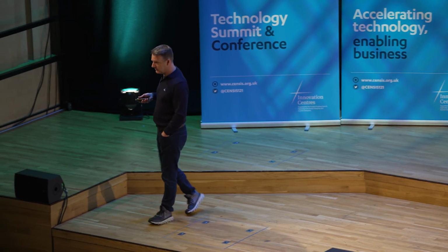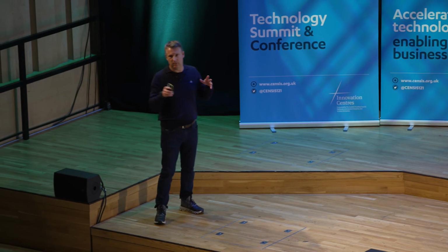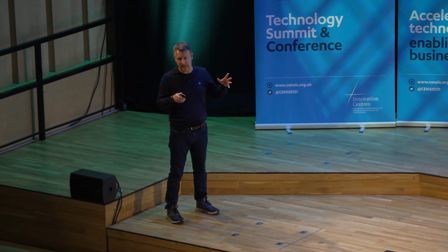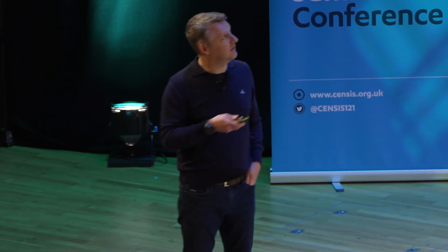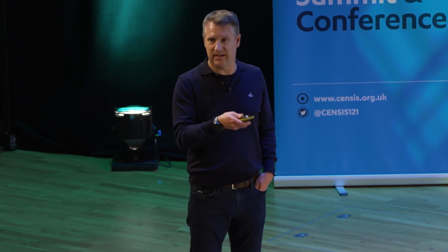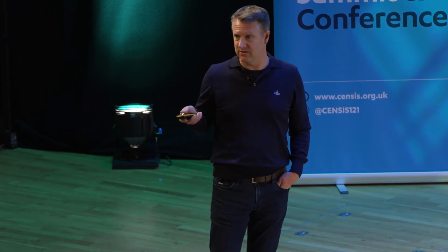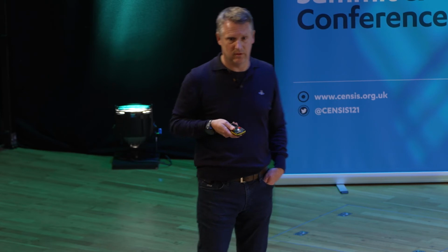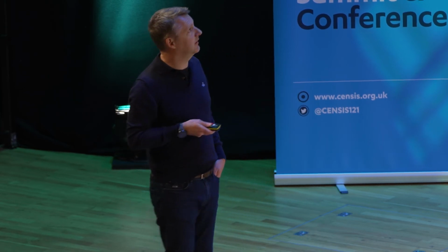But one of the problems is when you're putting on retrofit cladding, you're effectively putting a plastic bag over a building. And with that, you're trapping in moisture if the ventilation systems aren't up to scratch. So we were able to identify basically that this is what had happened. There were 10% higher humidity levels in some of the properties than had been there before. And that came down to the quality of the cladding.